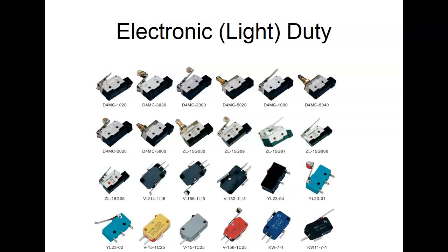What advantage does a limit switch have over a solid state limit switch? What would you think? Well, they got to switch power. We don't have to power them up to make it work. They switch the power. Okay, so that'd be one advantage, right? I'm going to put that note. Some switches are electromechanical, so they cost a lot less than their counterpart. These solid state limit switches are not very cheap.